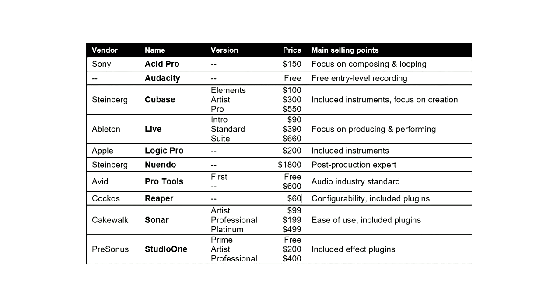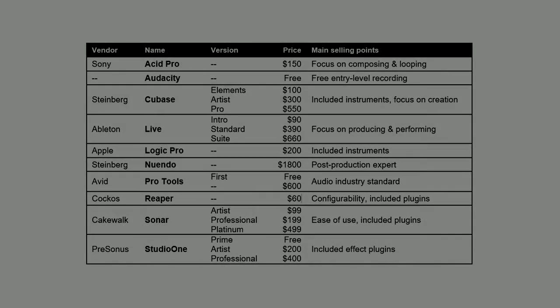Storing audio. What is the bit depth? The data captured from the sampling described in Chapter 3, Section 1 is digitally stored in numbers represented by bits. The total number of bits available to store the information contained in each sample is the bit depth BD. The larger the bit depth, the more amplitudes of that sample can be recorded and stored. Note that the bit depth does not impact the accuracy of the signal sampling. That is the job of the sampling rate.